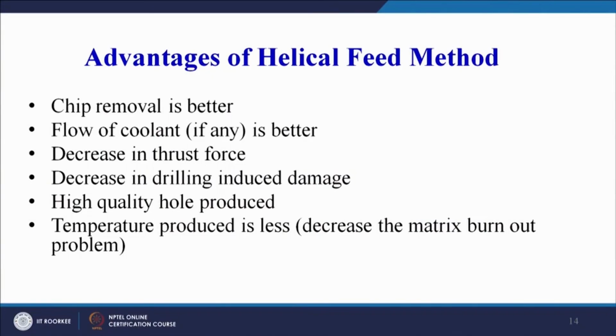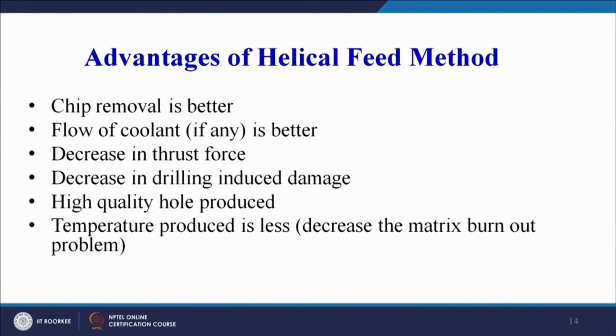Now what can be the advantages of the helical feed method? Chip removal is better because the chips get more space to come out from the hole area. Flow of the coolant is better. It can be very easily understood if you focus on the diagram, a very simple schematic that we have shown today. You can see that there is more area for the coolant to flow down.